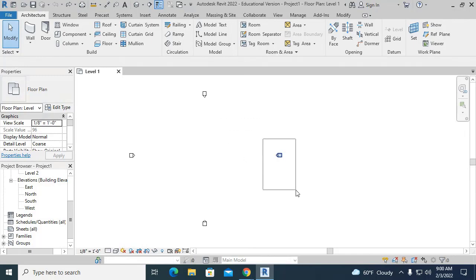Okay, on the window, I press down on my mouse and I'm just moving it. Don't let go of the mouse and you can move it. It's very similar to AutoCAD. If it's a solid box, it's got to cover the object completely. Very similar to AutoCAD, right? If it's a hidden line, so long as it touches it or covers it, it'll select it.